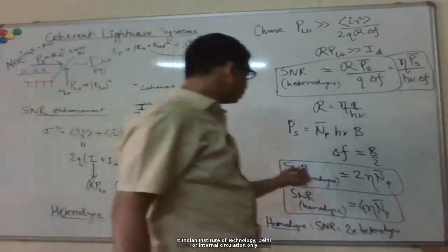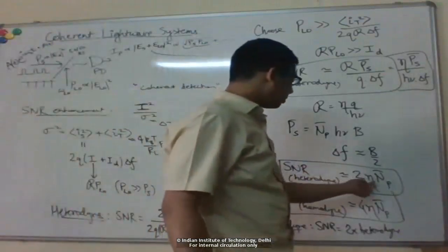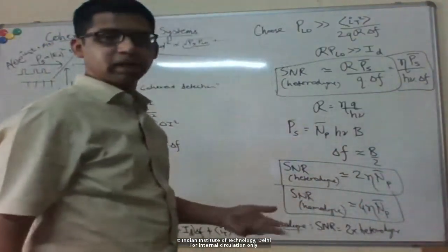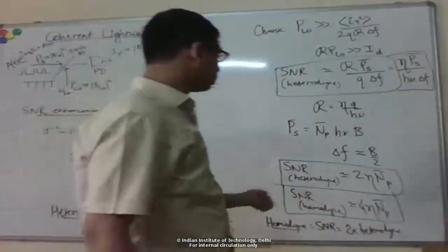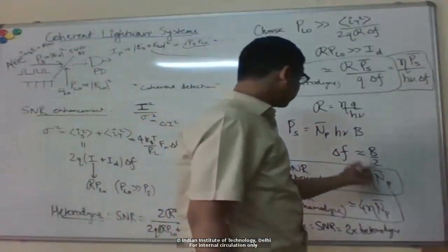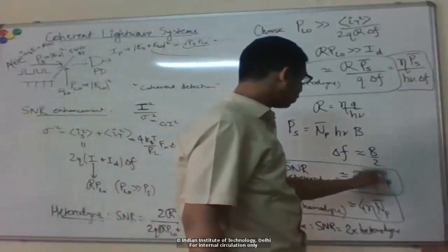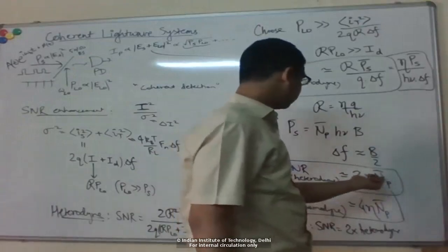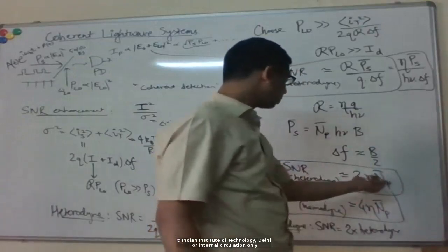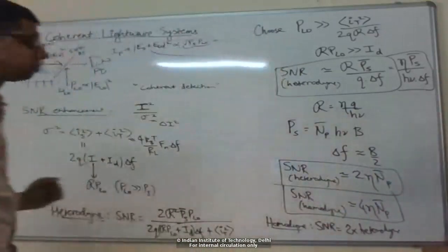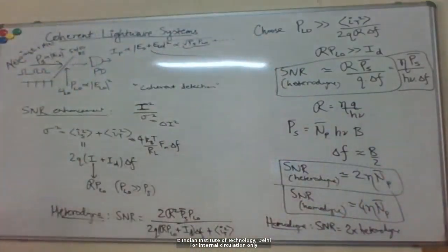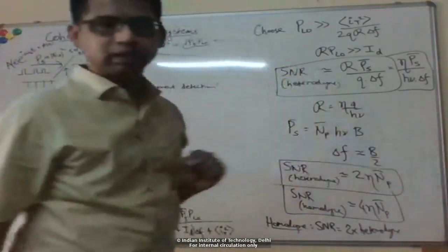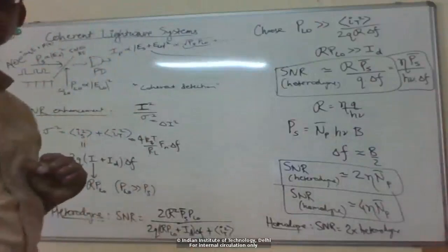So for example, again, quantum efficiency is typically between 70 to 90% for a typical InGaAs detector that we use, right? So you can see that if you roughly have, for example, 100 photons per bit, or let's say 50 photons per bit, then your SNR is already around 20 dB. Right? Compare it to the thermal noise limit where we needed, maybe roughly 2000 photons per bit.